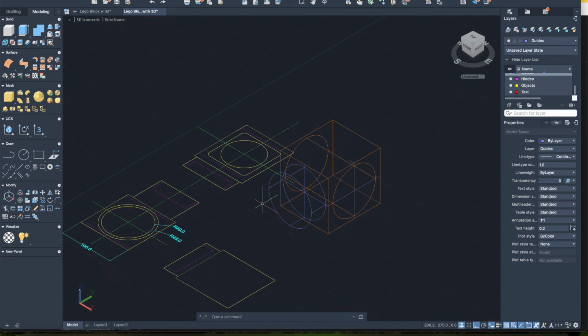Okay, and now there's an interior circle that you can see in the front view here that needs to be added on. It's another circle. I'm just going to go to my circle tool here and find that little plus, click on it, and put in 40.